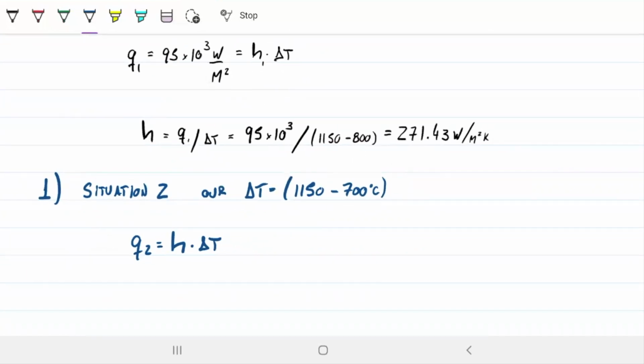To be able to answer that, what is our H2, we need to look at our Nusselt number. So let's look at Nusselt in the first situation and Nusselt in the second situation because we know they are the same according to what was said. And we know the Nusselt is the characteristic length times the convective coefficient divided by the conductivity, right?